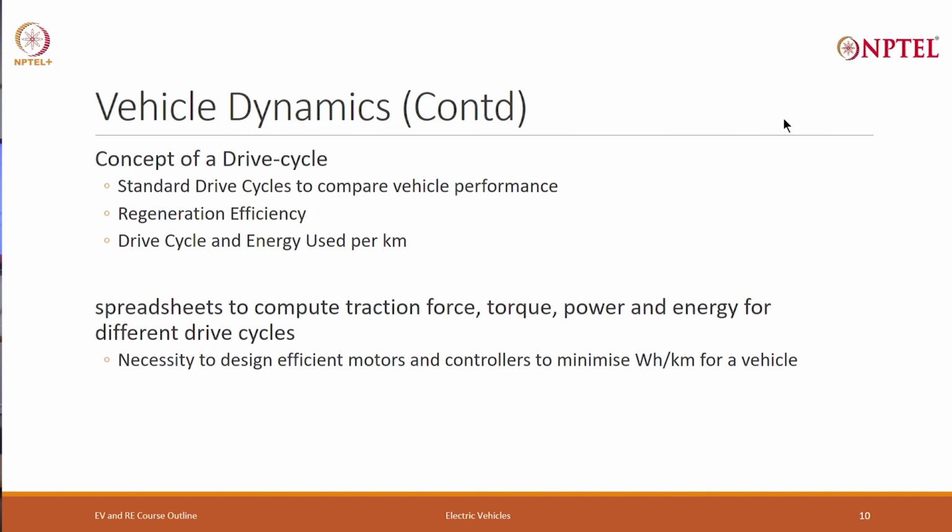And then we'll come to the concept of drive cycle and energy usage per kilometer. How much energy, how much electricity or how much petrol is used per kilometer by a specific vehicle in specific drive conditions. And as I pointed out, we'll use spreadsheets to compute traction force, torque, power, and energy for different drive cycles.